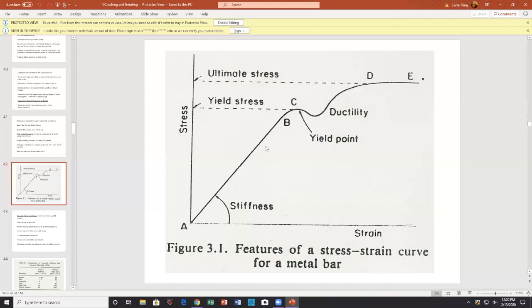The energy did not cause breakage. However, the energy went into the solid, right? Got absorbed into the solid, and the solid heated up because of the energy addition. So obviously, one of the really neat things you can do, if you have a high energy input to your solids without breakage, is to monitor the amount of energy that's being used to heat the material but not break the material. That's an inefficiency in the grinder, right?